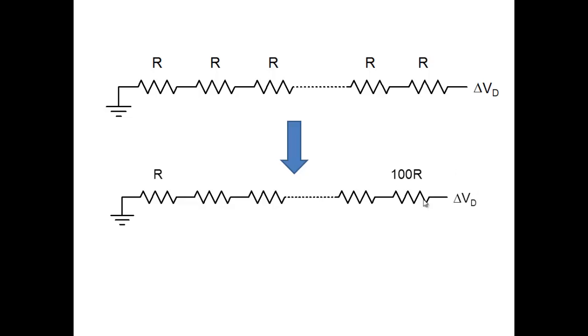It will all drop here, right? How much will be dropped across this? Negligible. And if negligible drops, the negligible drop divided by R is the increase in the current. So how much would the current increase? Negligible. So once you create a very high field region, all the extra voltage is dropping here, nothing is reaching this particular part. And the current tends to saturate. Current doesn't increase.